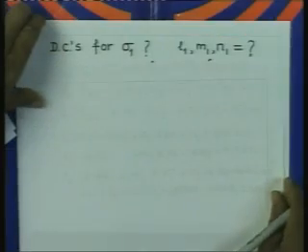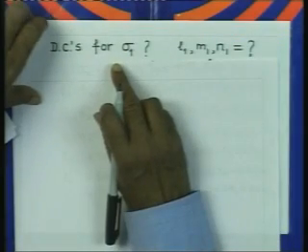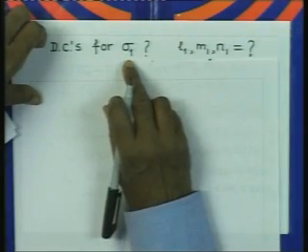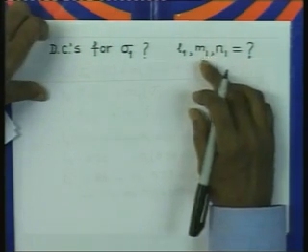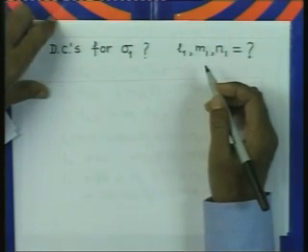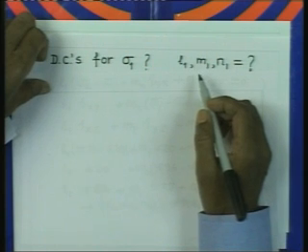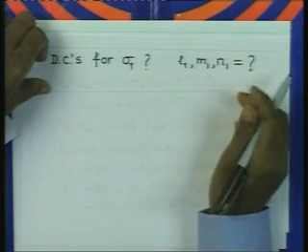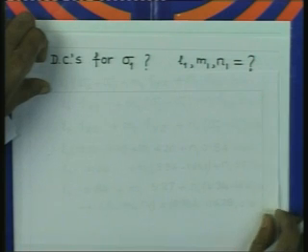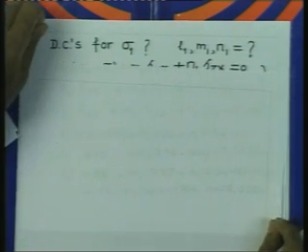So, once we have got the principal stresses, now we have to determine the direction cosines. That means we are interested in finding out what is the direction for the stress sigma 1. In other words, if we consider the direction cosines of the plane on which sigma 1 is acting is given by L1, M1 and N1, then what are the magnitudes of these three direction cosines?